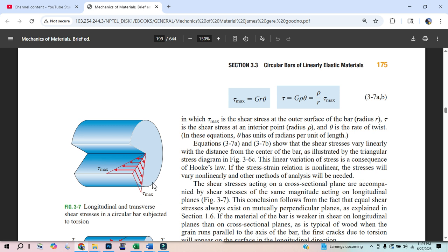So with this, you would crack on rings on the outer surface, because the outer surface is going to see the largest force. And then on this inner surface, these two surfaces are going to slide past each other. And so you can get longitudinal cracks. On this surface, you would get cracks in this up and down direction.